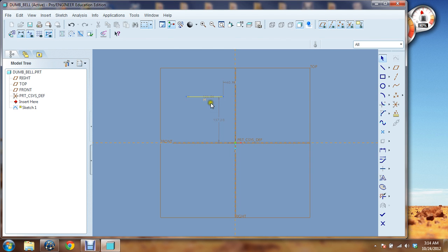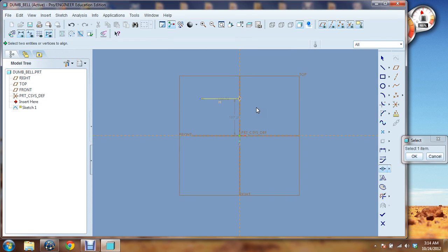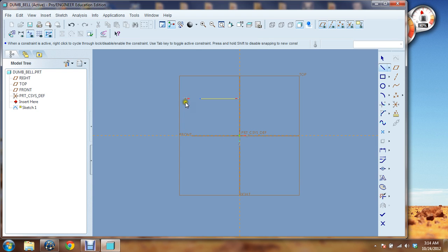So one thing I want to do now is show you the coincident constraint. You noticed before it was locking to the reference lines. We're going to go ahead and just do that ourselves instead of automatically doing that. I'm going to tell it go ahead and lock to that. Alright, and I'm going to go ahead and middle mouse click. And I'm going to go ahead and just take a line over here. We're going to draw another line. Kind of do that kind of quick.